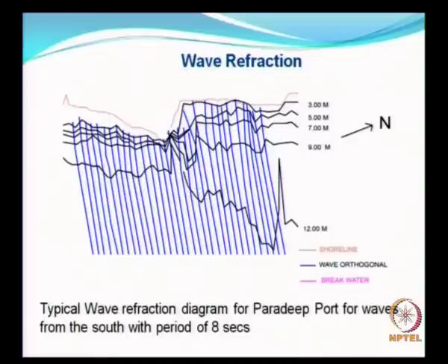So this is a typical refraction diagram, and this refraction diagram was drawn ages back, as early as the early 80s. These are all plotted by using a plotter, wherein I can show the breakwaters here. This was done for the Paradip port, and these are all the bathymetry. The 12 meters contour is quite haphazard, irregular,